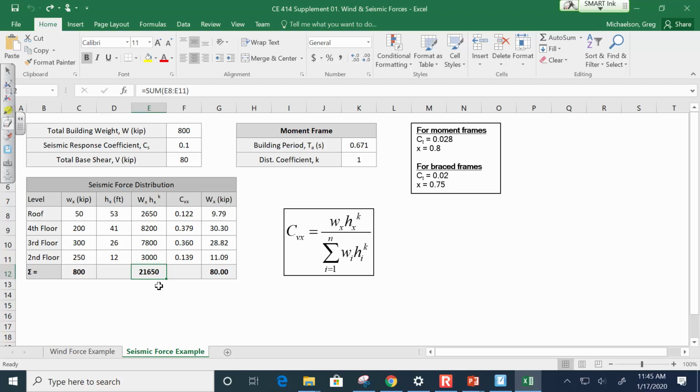So you're saying that you want the building to just sort of do that. In order for that to be the case, the beams would have to stretch. And I'm saying that they just won't stretch that much before they would snap. They'll bend, but not stretch. But there might be some ideas there. There are some systems that use base supports made out of synthetic rubbers, and the idea is that they'll allow a little bit of movement.